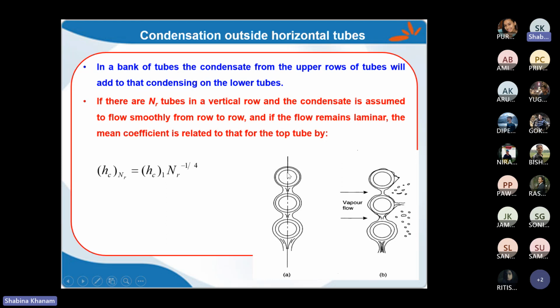NR is the number of vertical tube rows at the middle or at the center of the bundle. You have already understood the NCV and NWV calculation, right? NCV is the space between baffle tips divided by PT prime.